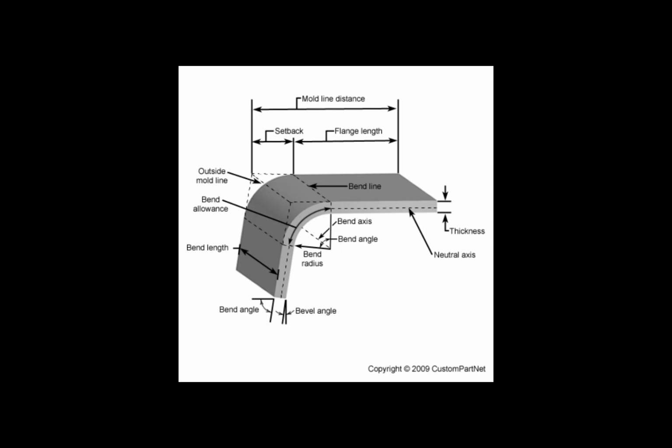What do you do to a drill bit before drilling plexiglass? Modify drill bit to a 60-degree tip angle.